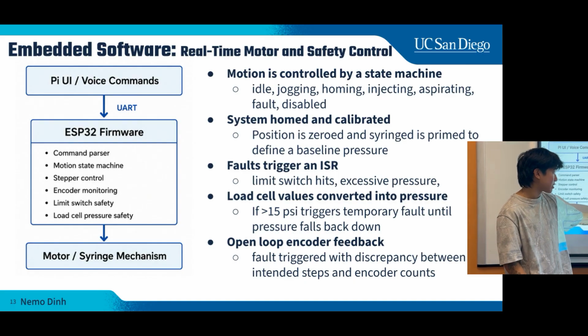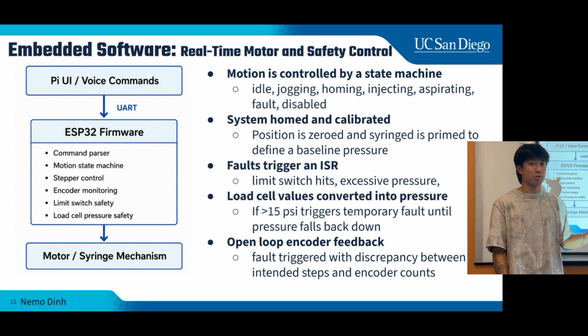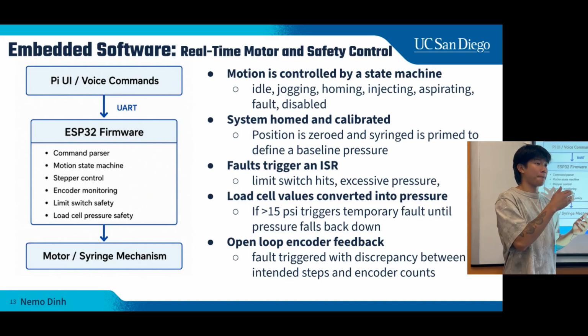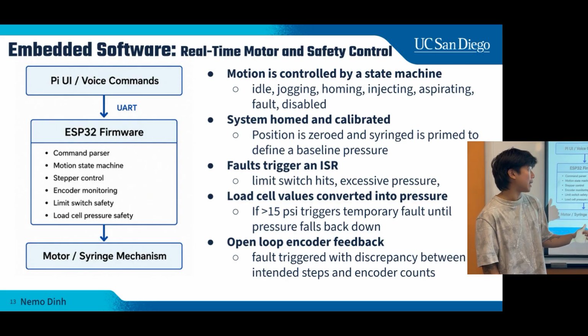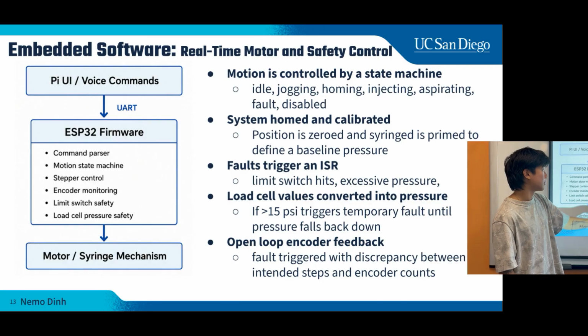Pressure also works like this. If the pressure calculated on the ESP exceeds the pressure threshold, which is usually 15 psi, it will stay in a temporary fault state until the pressure falls back down, and then it goes back to idle, and it will then accept more commands.